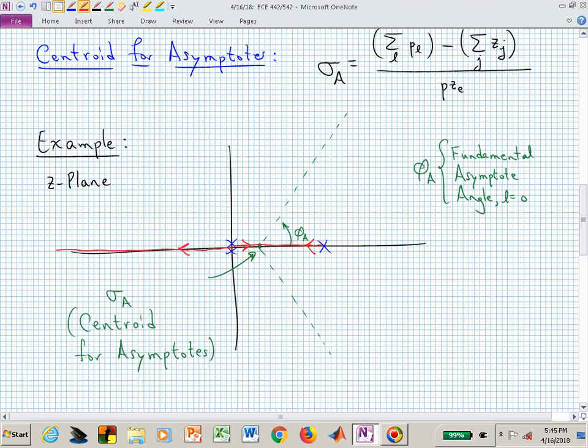So our breakaway points and re-entry points, that's rule number 3, apply to poles and zeros. Now, what's going to happen between those 2 poles at the origin and the pole to the right? We have 2 branches coming together. They can't stay stuck at one location, can they?